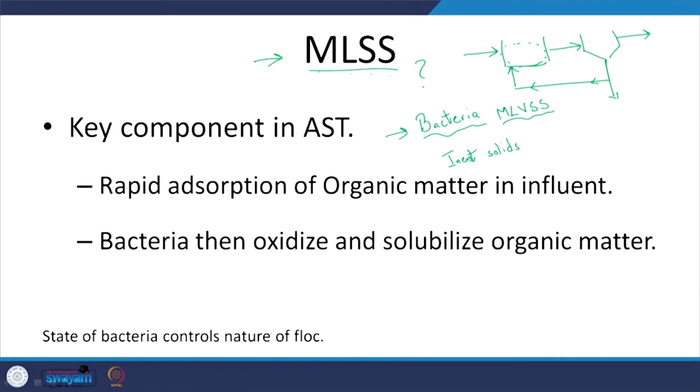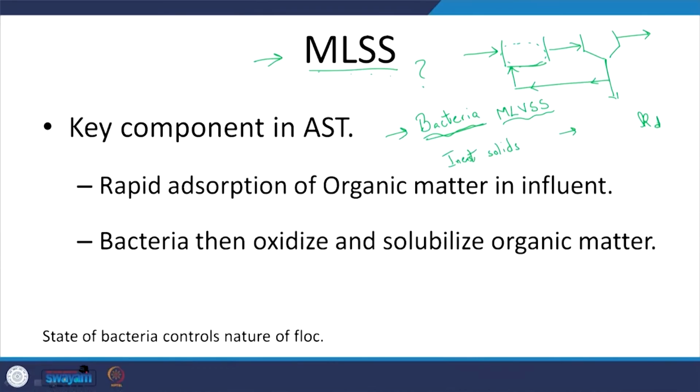And in this MLSS, what else? Is it only bacteria? No, you will have some protozoa, 5%, and they also feed on the bacteria. So that's why you have the decay coefficient Kd, right? So that's one aspect, and protozoa seem to be playing an important role in leading to good sludge that can settle. So that's one aspect.